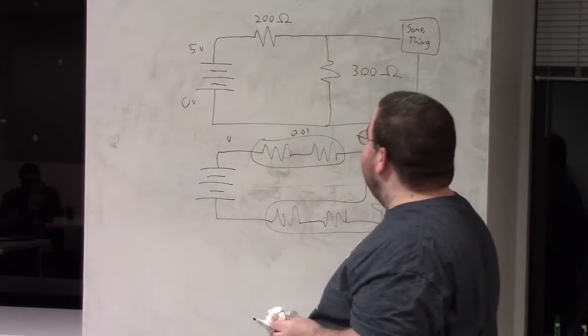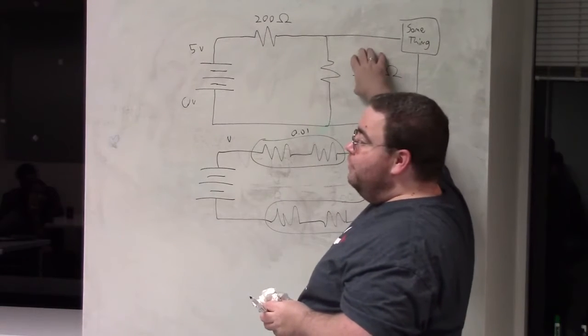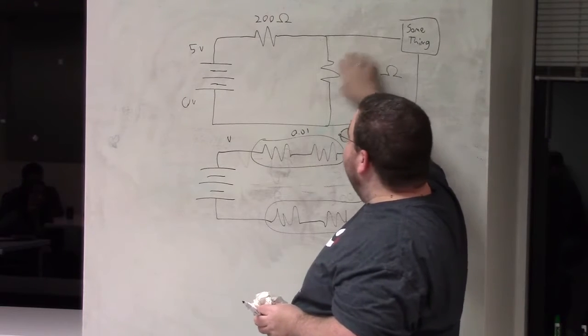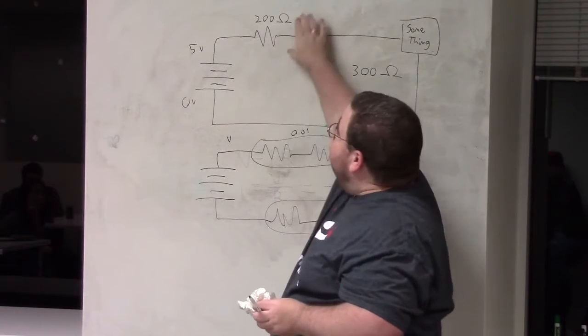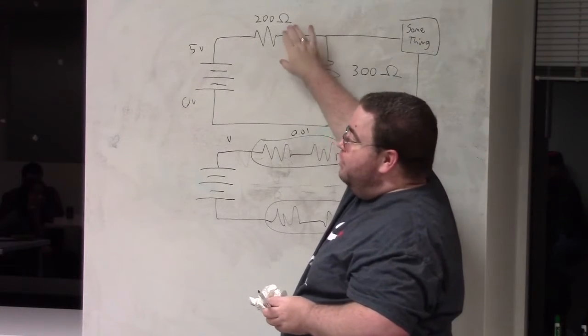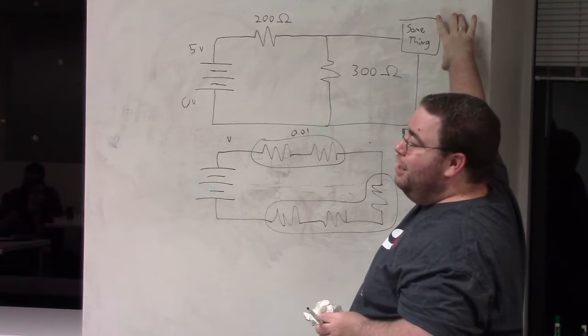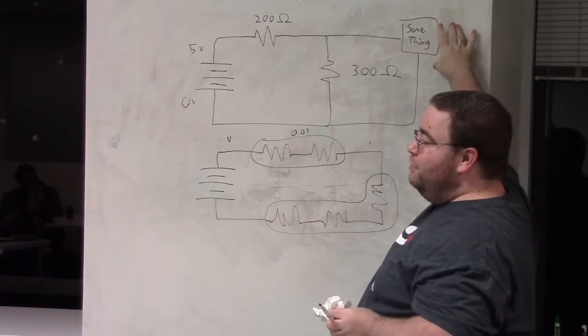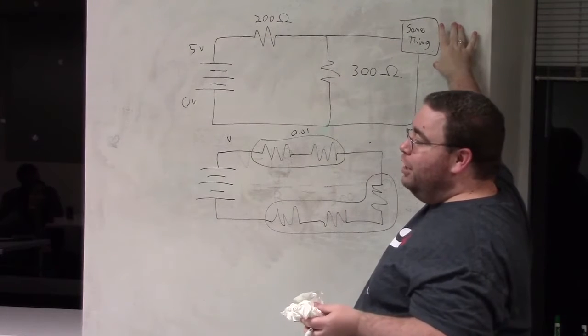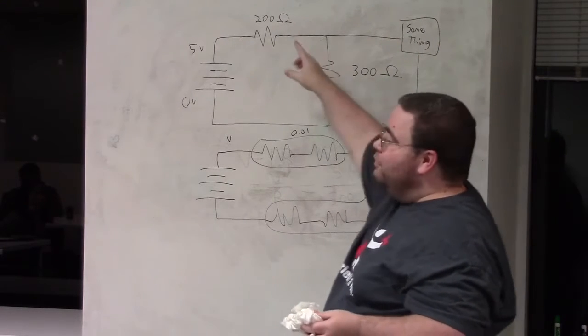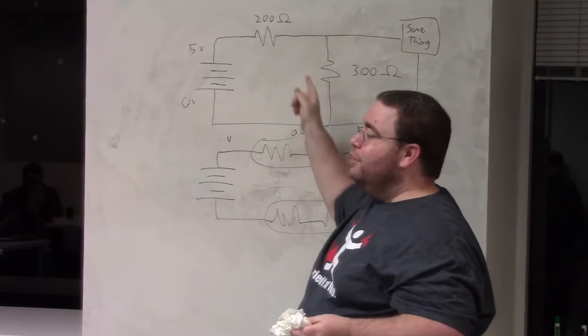The problem is that whenever you increase this to lower the amount that you're dropping off, you have to increase this also, which is going to decrease the total current that gets to the thing you're trying to power. And so if you have a chip or something that needs at least 50 milliamps to run, then you need to have small enough resistors here that you're going to be wasting a large amount of current.